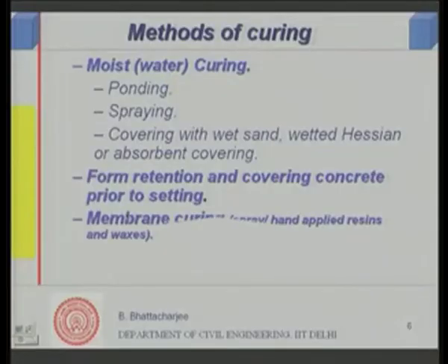What about self desiccation? That water will still be consumed by the concrete internally. So, relative humidity will not be 100%, it will not be as good as spraying water or replenishing the water, but it would be better than not having anything, right. So, you can retain the form, cover the concrete, and then there is something called membrane curing.